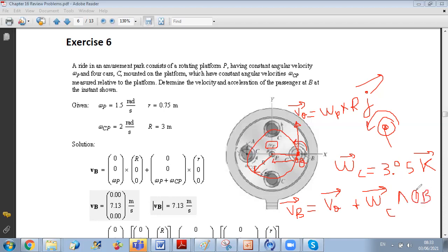So now if I replace, this is what they did here, guys. Look, this term is velocity of O. How do we get velocity of O? Now we did the method of magnitude and the right-hand rule. Then to find VO, they did the vectorial method. If you want to do the vectorial method to find VO, VO is Vp, which is 0 because P is fixed, plus omega of the plate vectorial PO.